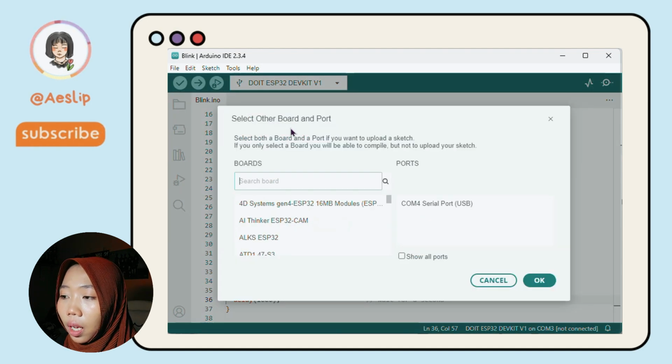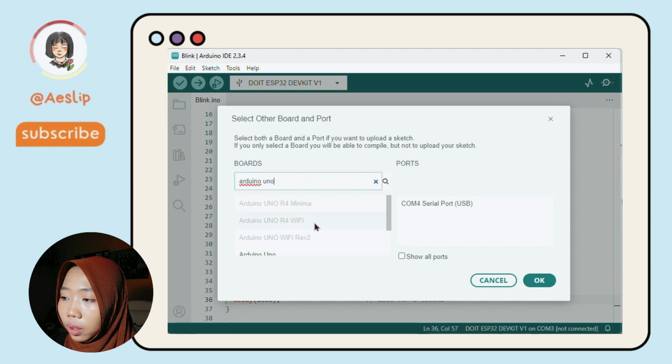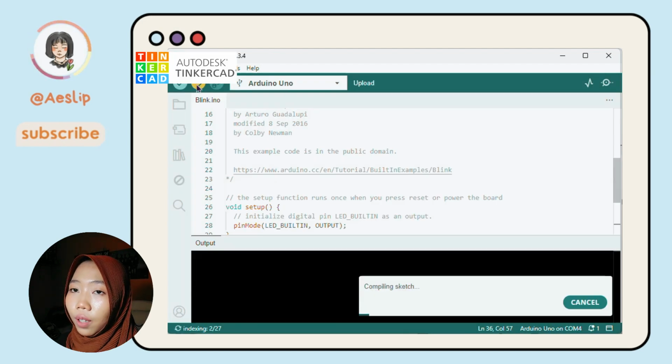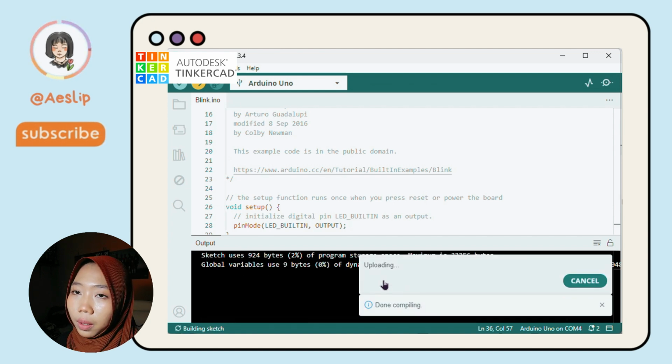After installation, try unplugging and plugging the Arduino back in. Open Arduino IDE, Tools, Port, and select the appropriate port. If it appears, try uploading the Blink code again. Okay? If you have any trouble, you can comment in the comment section below.